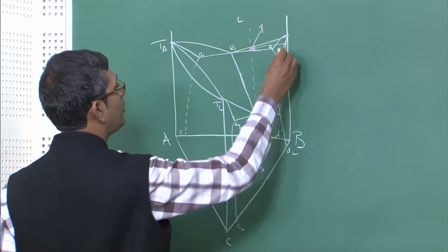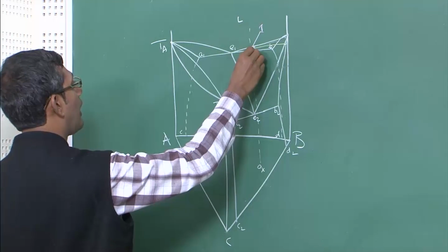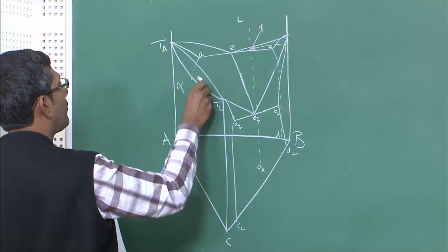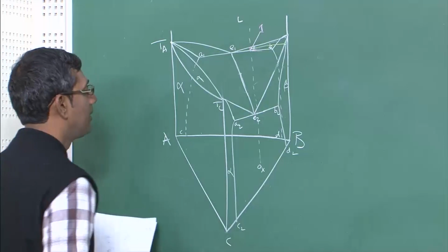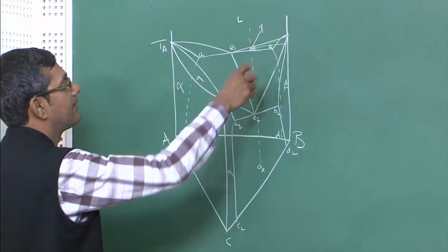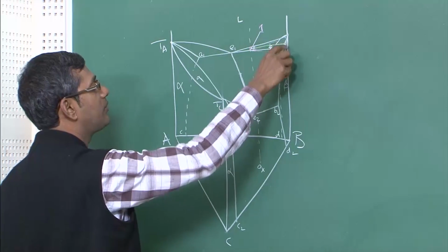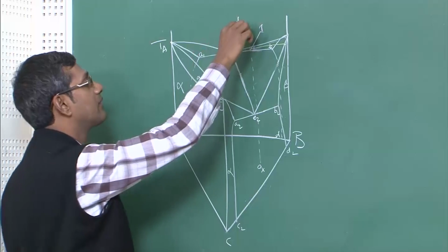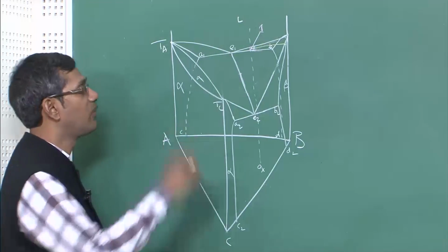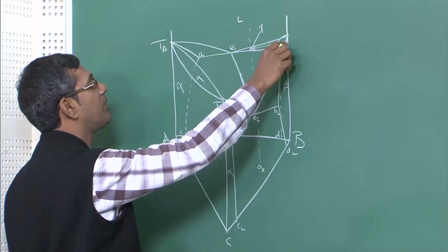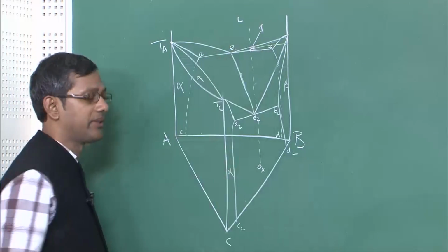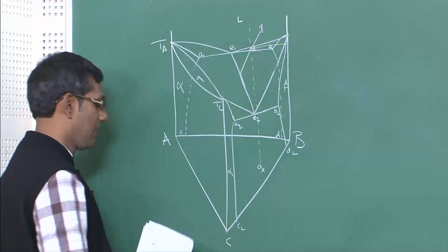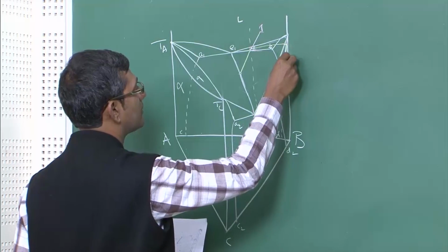This is the surface on which this will be in equilibrium. This is the alpha, this is the beta phase rather, because this is the beta, this is alpha. So, this is the composition of the beta phase which will form on the surface of the liquidus. When you cool down to the liquidus temperature, this is the composition of the beta phase, which is B-rich obviously, and the liquid phase. Now, as you cool it down, this is the way the liquid composition will change, correct. Similarly, this is the way the solid composition will change, correct.